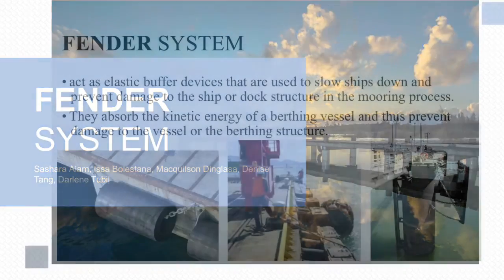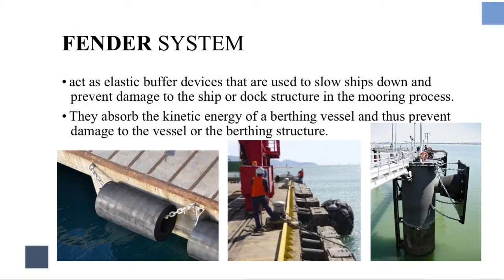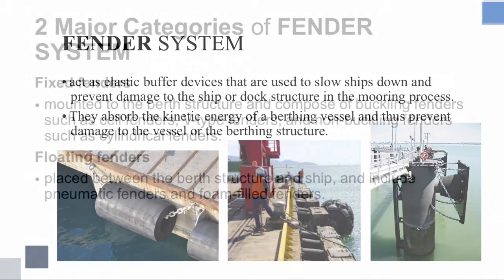Fender system. Fenders act as elastic buffer devices that are used to slow ships down and prevent damage to the ship or dock structure in the mooring process. They absorb the kinetic energy of the berthing vessel and thus prevent damage to the vessel or the berthing structure.